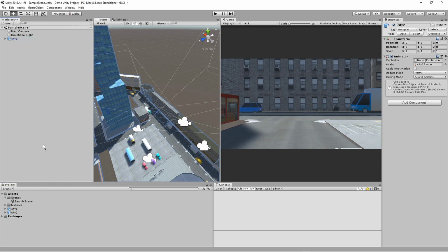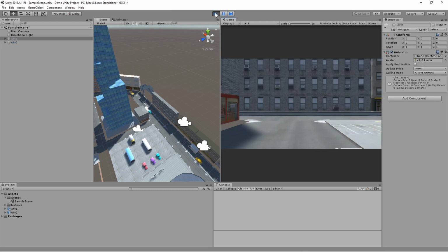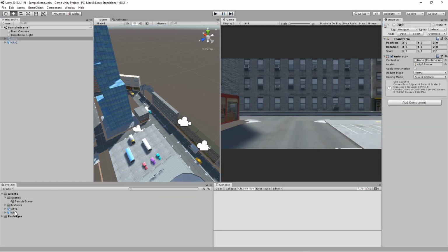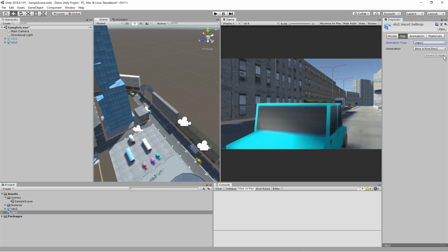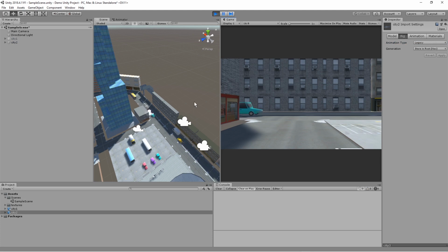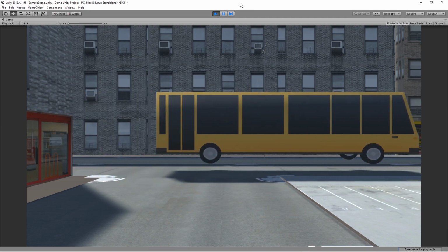It's just importing that file. So I drop that into the scene and turn City 1 off. And now again, if I play, it won't move. But this time, if I change the animation type to Legacy and press Apply, then hopefully we'll get the cars moving. So we get that camera shot there, getting this all starting to work. If I do maximize on play, I'll be able to see that in full screen. So potentially that's a real-time rendered version of the animation.